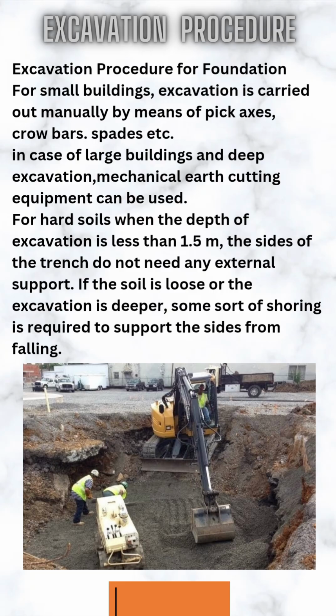Before excavation there are a lot of procedures we need to follow, but excavation is among them. For doing excavation there will be site clearance and many more things that we need to follow. If the ground is undulated we need to make it plain. We will discuss only the procedure which we need to follow for the excavation, or we can say the excavation procedure for the foundation.